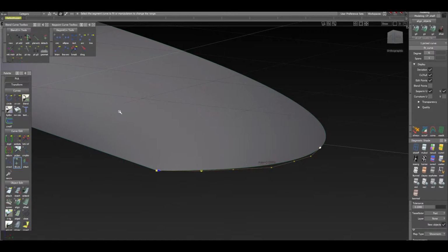And now we're going to create a construction plane. Why are we going to create a construction plane? We're going to create a construction plane because we need to create the base of our tube, the base of our pipe, which is going to act as a sort of springboard. Okay, no pun intended. It's also going to allow us to draw a circle on that construction plane, which will set the radius or the actual width of our spring, of our tube.